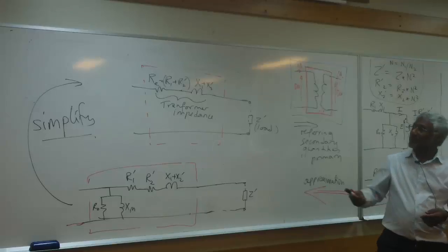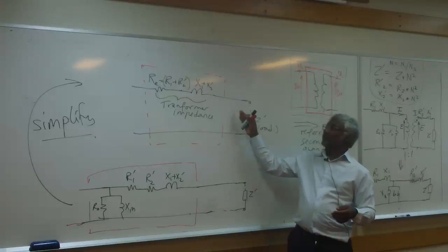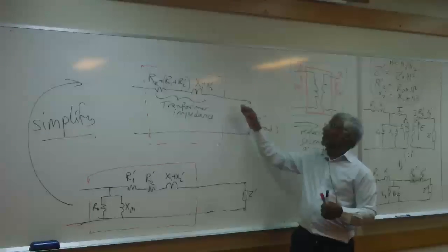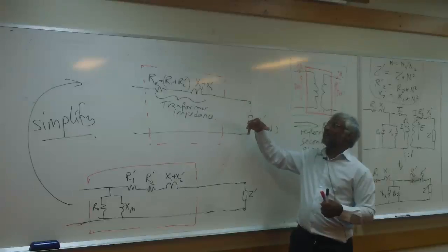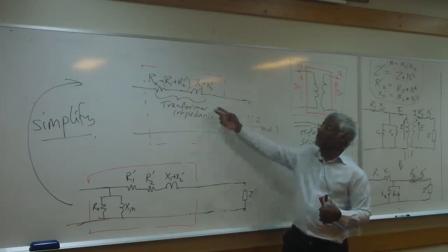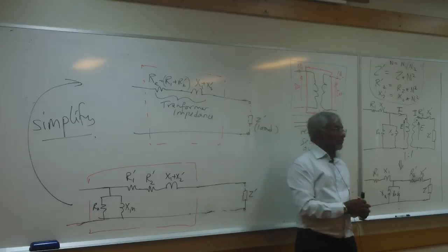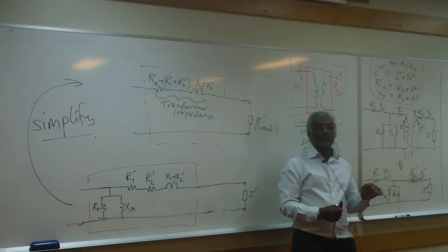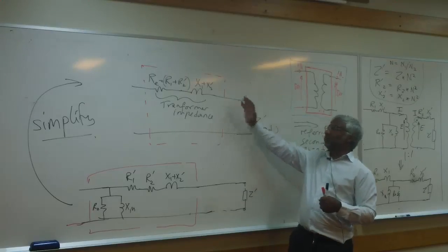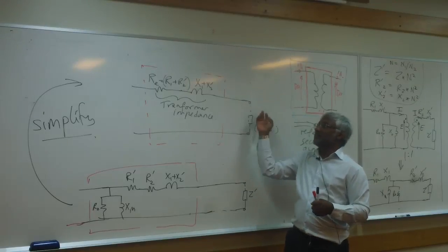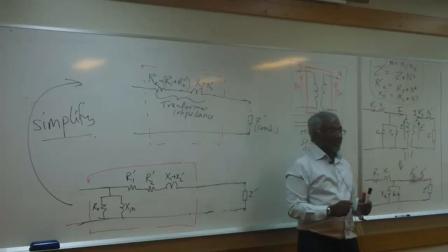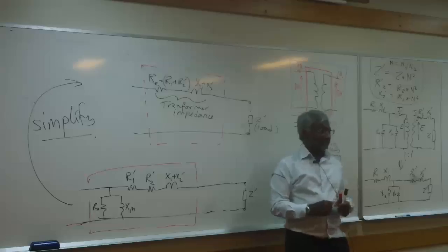For faults that are happening on the secondary side, your circuit breaker cost could be reduced by having more leakage in the transformer. That is your fault level. The fault level on the secondary side can be reduced by having a transformer with a higher leakage.